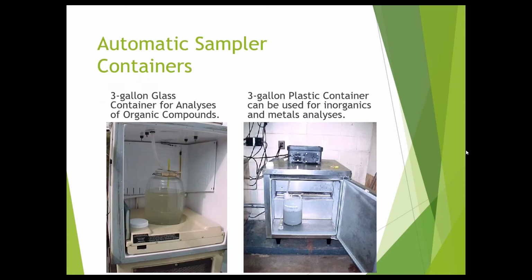Okay, I have a couple of questions. How do you determine the sample collection time from the start of the composite or the end of the composite in order to determine the holding time? So I normally use the last sample on the composite as the start of my holding time. That's just what I use. Some people would like to use the first one. As long as you're consistent, be consistent.